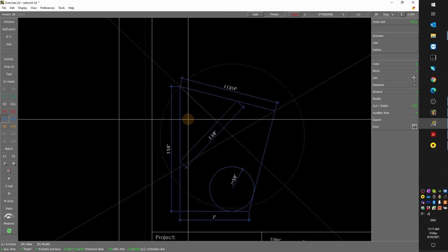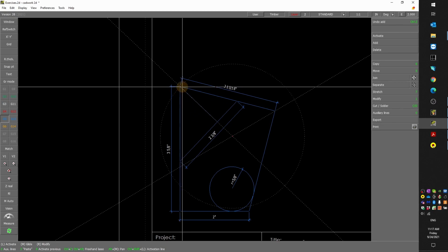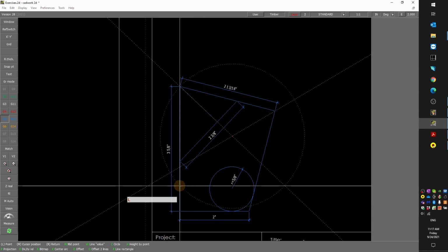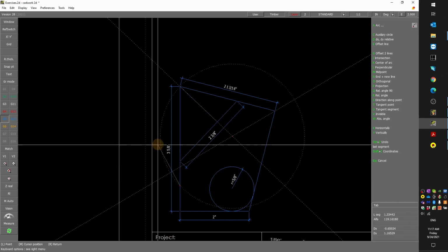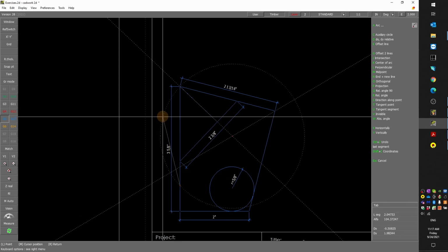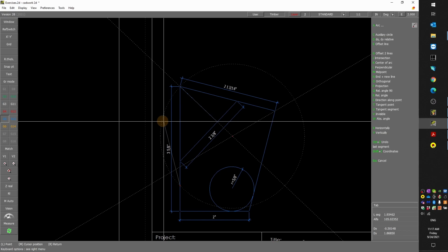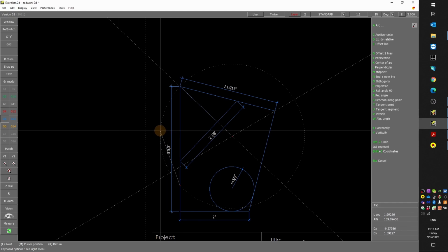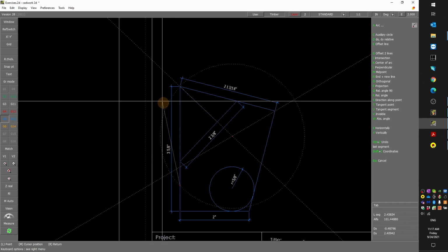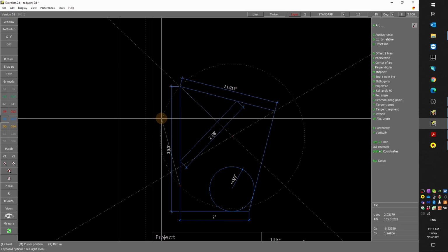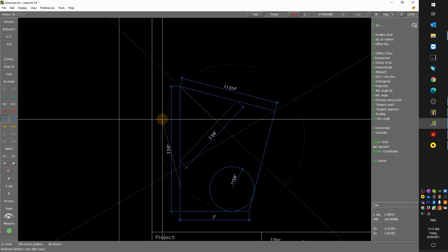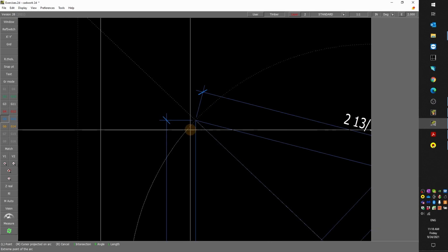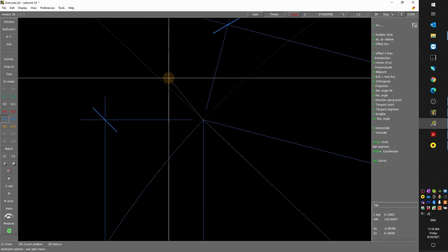So here I have different options to create that arc of a circle. Which starts here or down here. So it's a line. I press L and then I left click on the intersection. Now I would like to follow this auxiliary line. So the shortcut is C to follow an auxiliary circle. You could have multiple circles, and then each time you want to follow a circle, you have to point the cursor on the circle and press C. And now you see as soon as you press C, it's following the line, and I can left click to fix it.